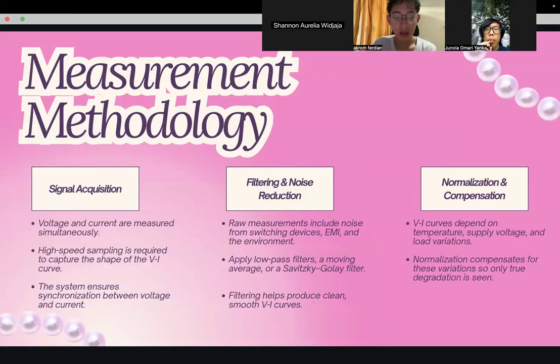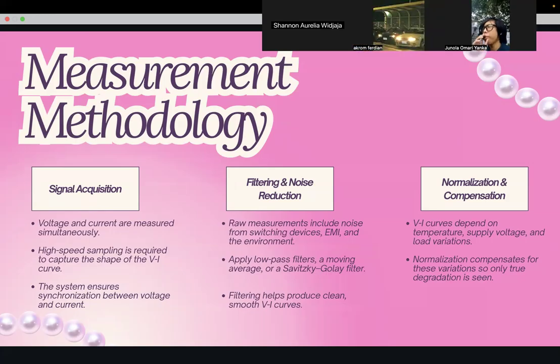And now the measurement methodology of our power monitoring system. The first method is signal acquisition. The voltage and current of the system being monitored are measured simultaneously, and high-speed sampling is required to capture the shape of the VI curve.